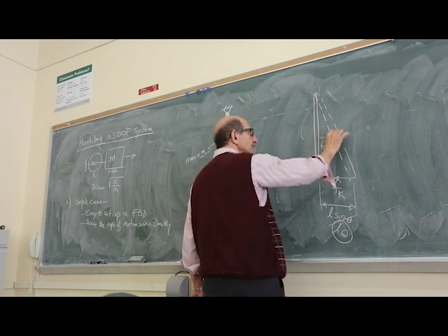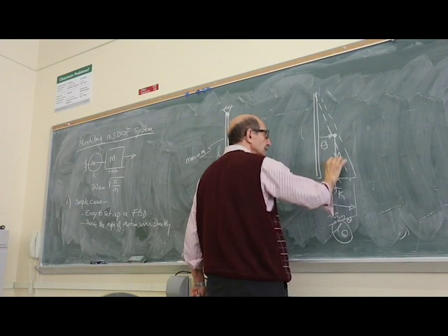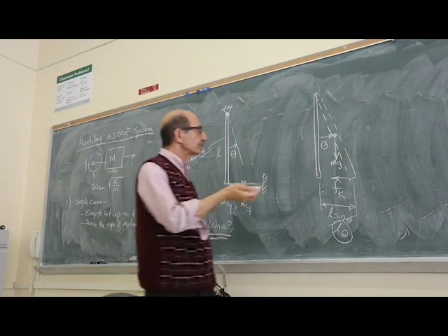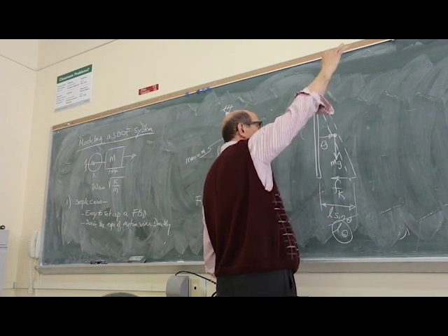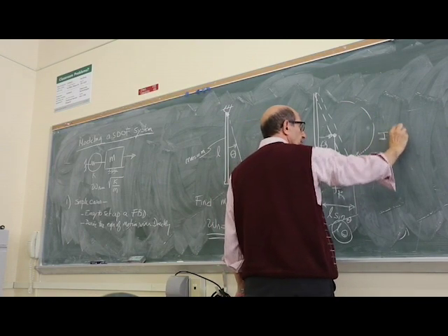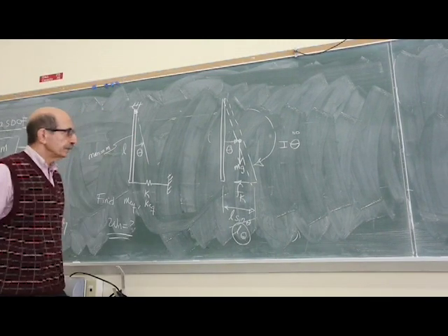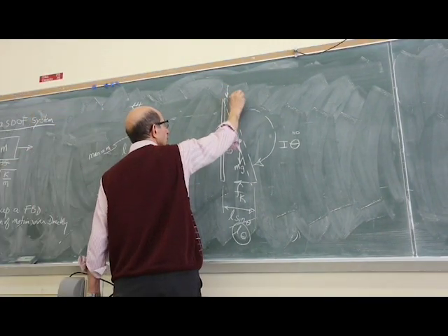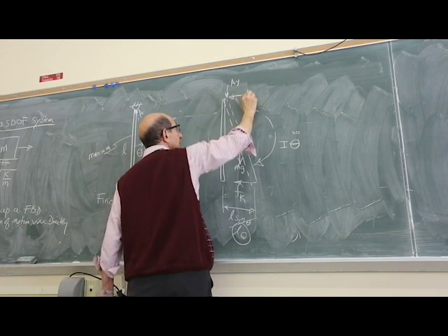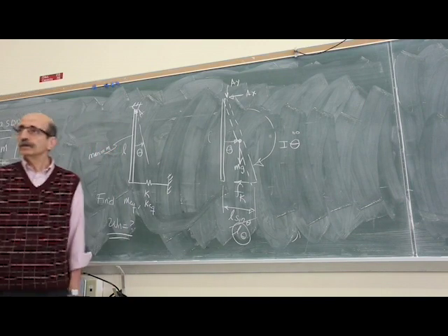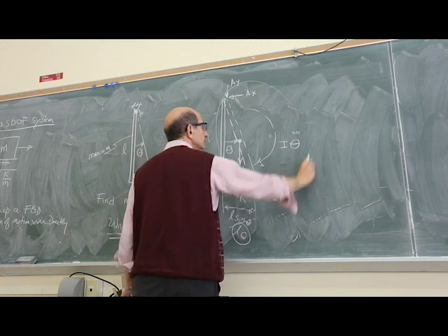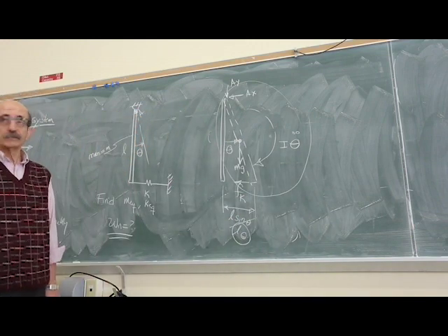Then you have this mass acting through the center of mass, so that's another force, and this is moving in that direction, so you do have also an inertial force, rotational inertia, like this. And you have these 2 forces that are holding this, if this is A, AY and AX, that are holding this bar in place. So this is the free body diagram, using the D'Alembert principle.